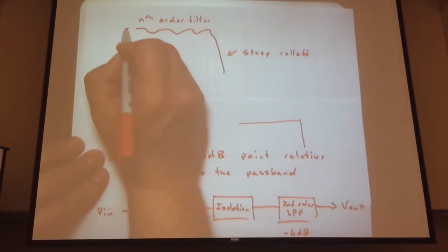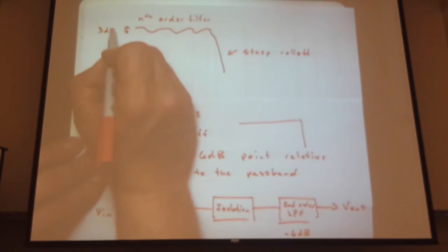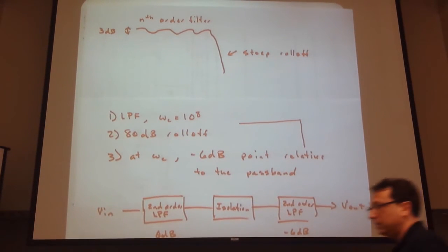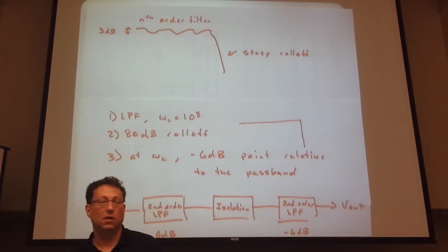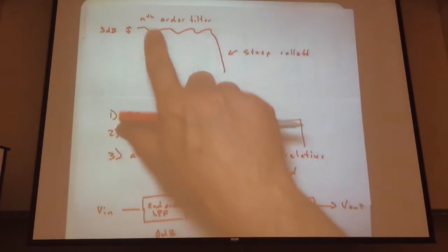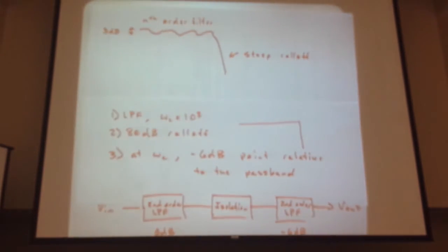And the variation in this region, this oscillation, is a 3 dB variation. That's a design criterion, because that's been agreed on as an acceptable range of values. That's a 3 dB variation from these poles and zeros as things go up and down, and that's acceptable.